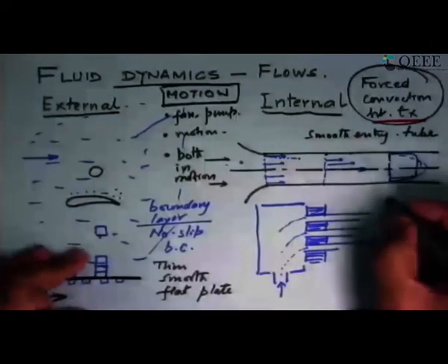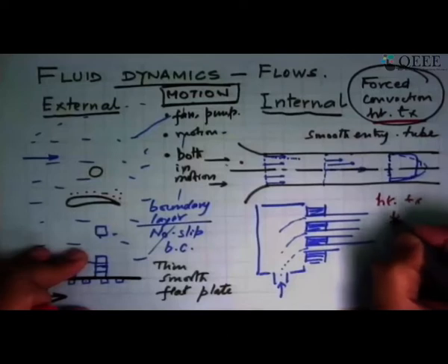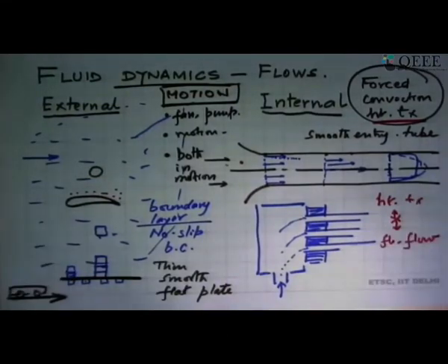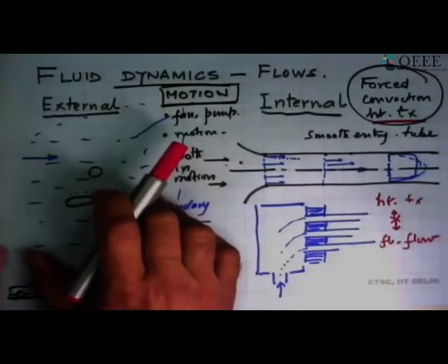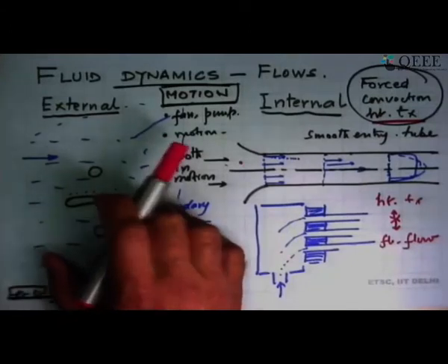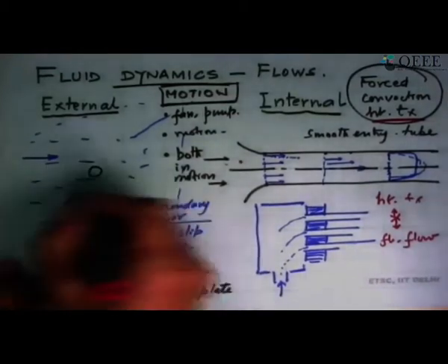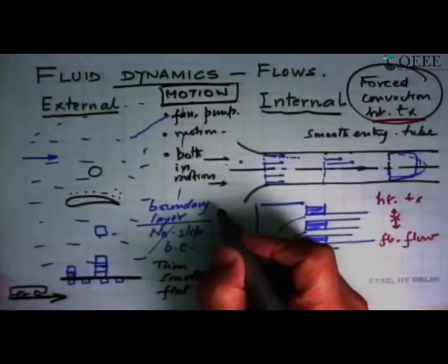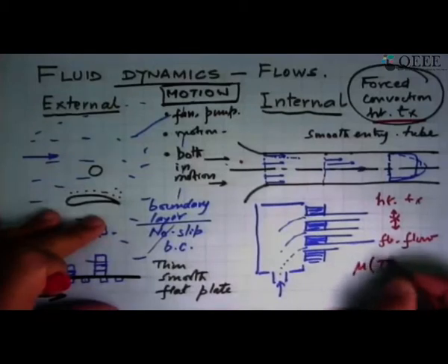So the heat transfer effect is delinked from the fluid flow. That means the conservation of mass and momentum equations that one solved in fluid mechanics would still be applicable here. They do not have any dependence on temperature, except in one way: the fluid that came here, its temperature changed. That temperature change caused a change in the properties of the fluid itself.